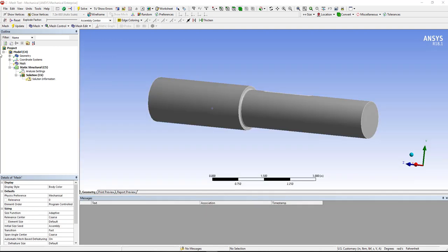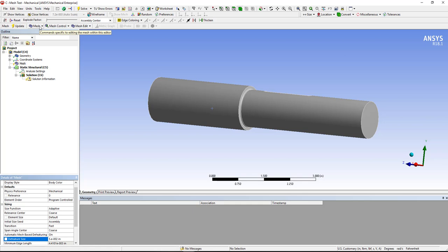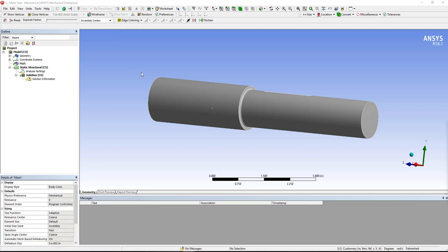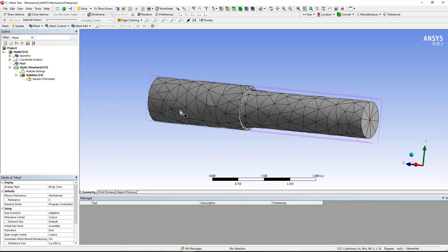Okay, so let's look at a few other meshing things that we can do here. One, in our mesh, sometimes you don't care about features smaller than a particular size. So you could come down here to feature size and maybe make it 0.05 and create a mesh, and that would allow it to simplify around small features that don't need to be resolved in the mesh. And it will simplify your mesh, though you're not going to get as accurate results around those areas.